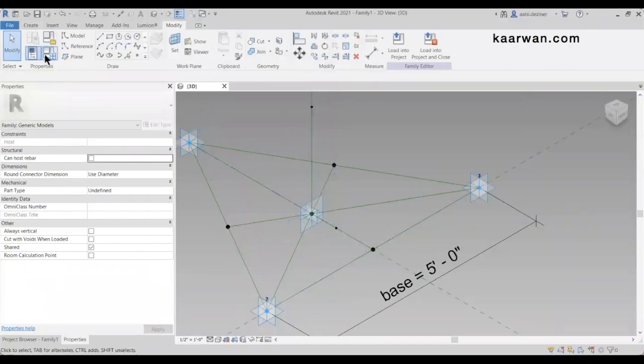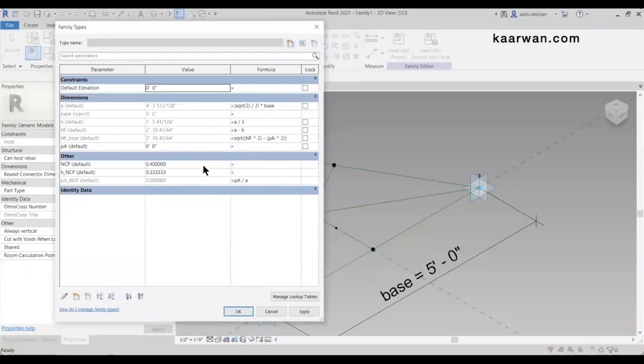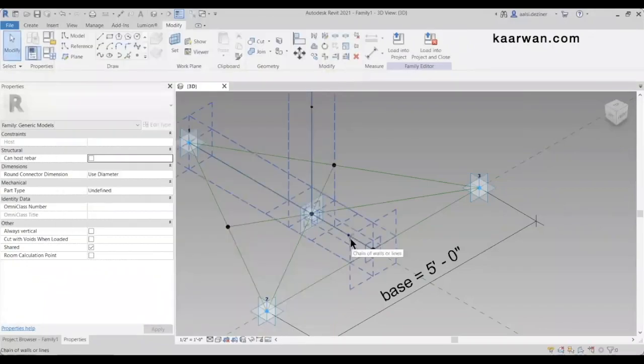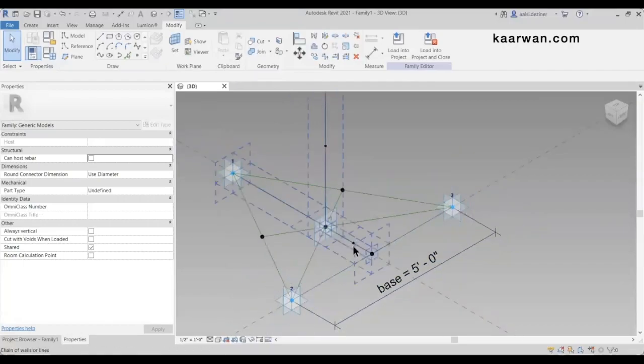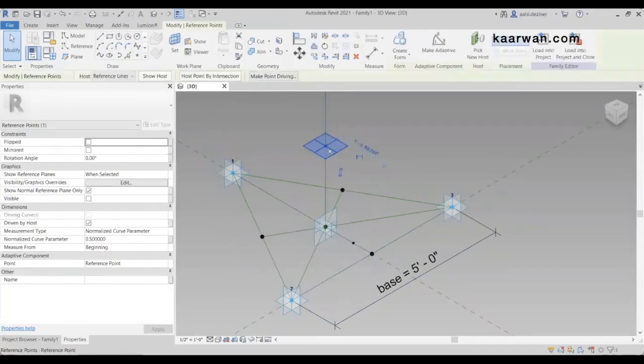You saw that the point moved. The point is moving with the NCP value changing from 0 to 1. This is our critical control point to alter the shape of the entire kinetic facade element. Make sure you change the values every time you add a few parameters, and check that it's going in the right direction and all the formulas are working.